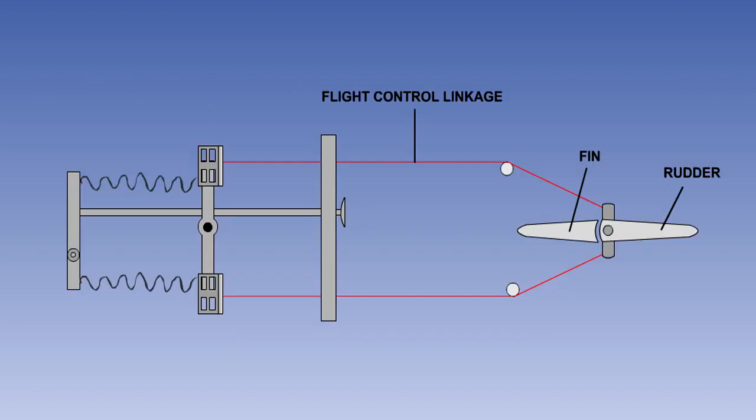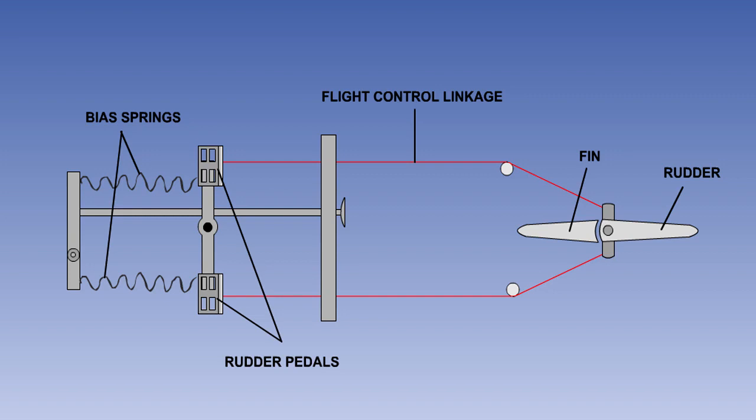In the spring bias type of trim system, an adjustable spring is used to reduce the stick force. No tabs are required, so the spring system does not have the disadvantages associated with tabs. The spring bias system differs from the other systems discussed so far, in that the device is connected not to the flying control surface, but to the pilot's control. The trim control biases springs which apply a force to the control linkage to oppose the stick force.